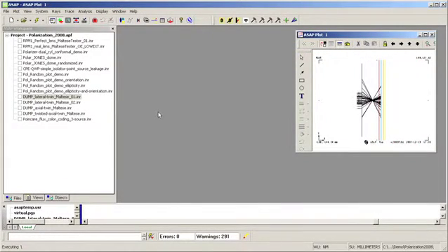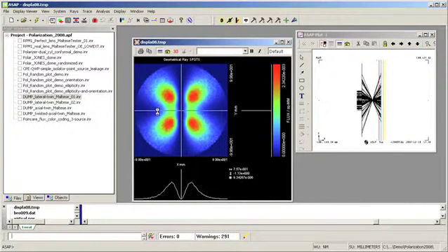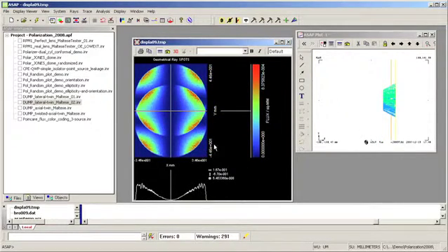Another enhancement allows polarization information to be saved with ray set data using the dump command and then reloaded using the emitting data command. Two sources with a slight lateral offset between them can be created using this technique, resulting in a smeared Maltese cross. The same technique with a narrower beam results in separated Maltese cross patterns for the two sources.